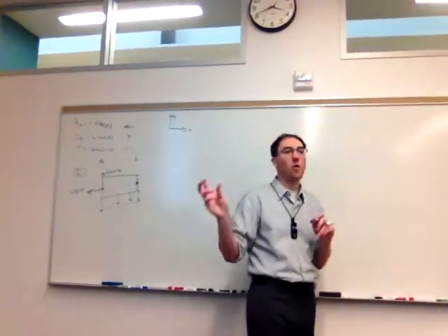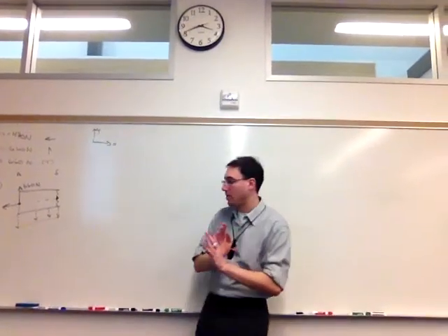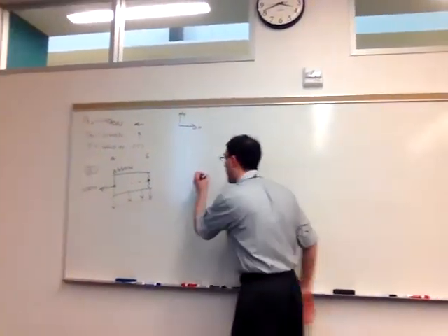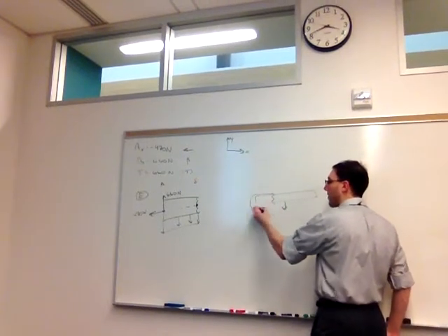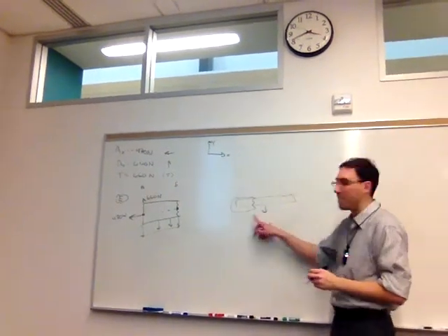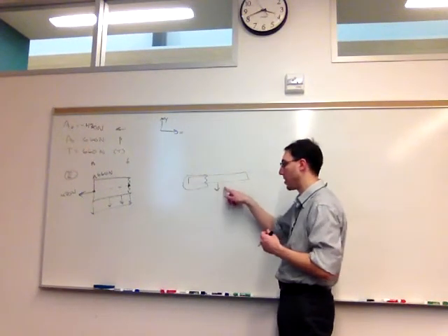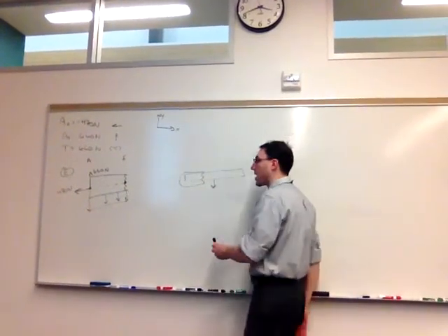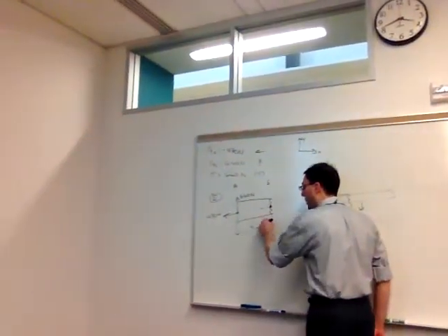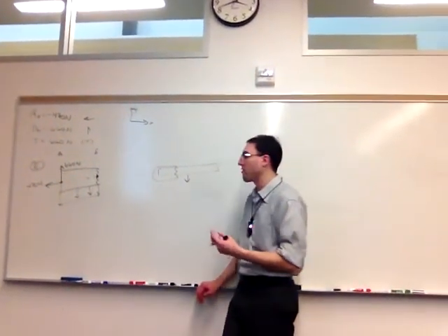We don't want to take our original picture, simplify it to the point load, and then use that picture to draw this, because if we did that in that beam, if we're cutting through E and keeping everything to the left, in the simplified picture, there is no load. It can't see the distributed load. It's all right here. So that's why we always have to go back to that original picture and cut through it. And now in that picture, we see that some of the distributed load was acting on the beam from A to E.